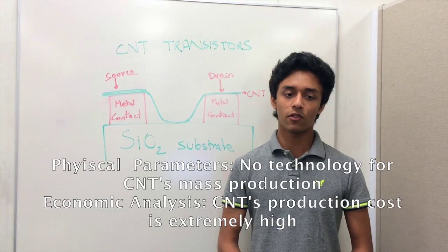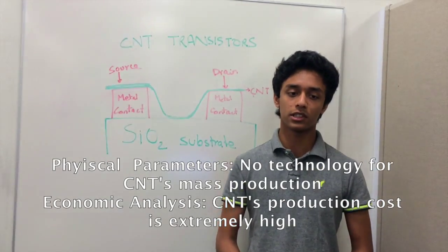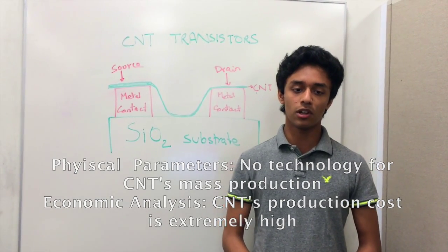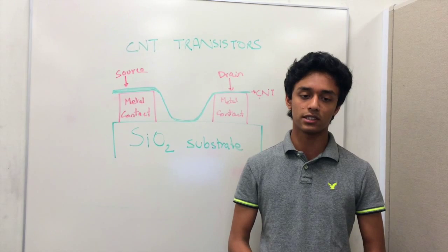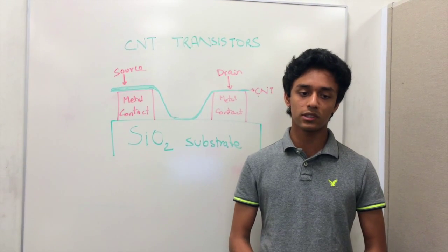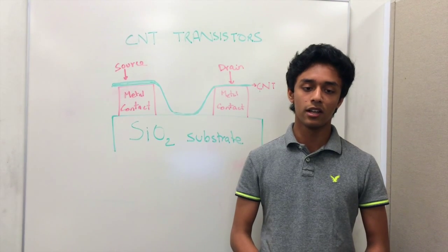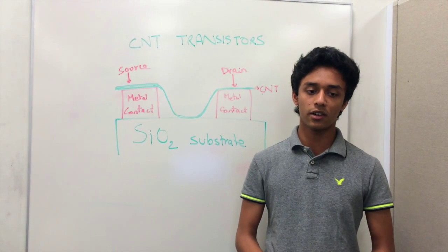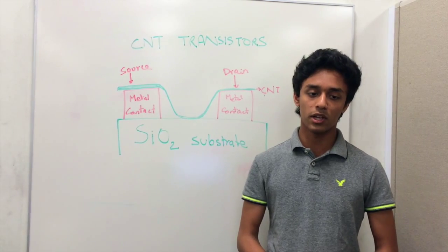The biggest disadvantages of carbon nanotubes are that currently no technology exists for their mass production, and high production costs. Another issue is that smaller transistors require smaller contacts, and shrinking those contacts shoots up resistance. However, that problem has recently been solved using molybdenum contacts that have been chemically bonded to the CNTs. Further shrinking of the transistors will cause more problems like quantum tunneling that we are not equipped to deal with.